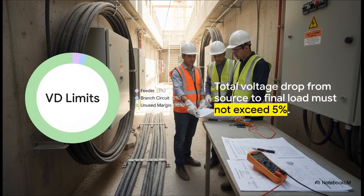The SEC is incredibly strict about voltage drop, and for good reason. It protects motors and sensitive electronics. The rules are simple and firm. You can't have more than a 3% drop on your main feeder, and from the source all the way to the farthest outlet, the total drop can't be more than 5%. Your voltage drop calculation sheets are a critical part of your submission package.